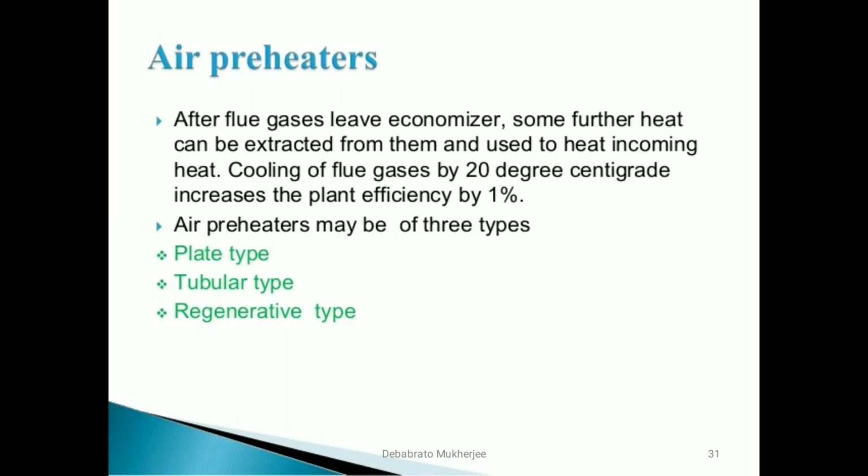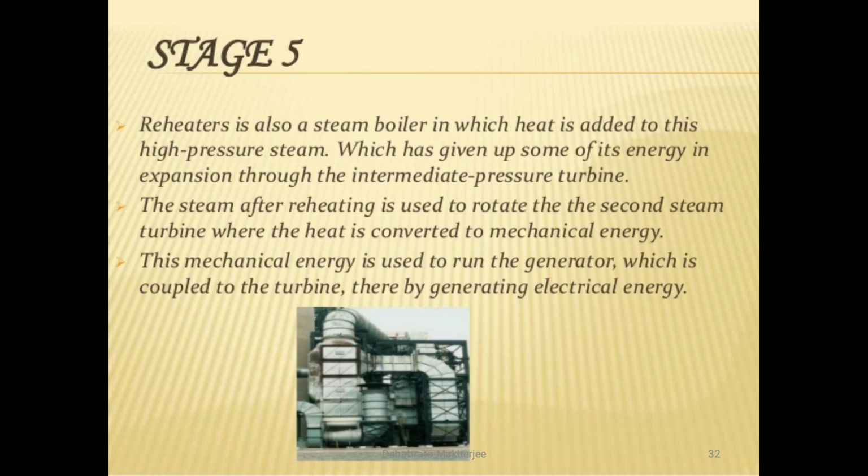Air preheater. An air preheater may be of three types. Generally, after flue gases leave the economizer, some further heat can be extracted from them and used to heat the incoming air. Cooling of flue gases by 20 degrees centigrade may increase the plant efficiency by 1%.